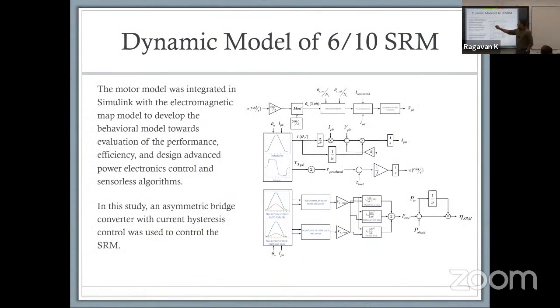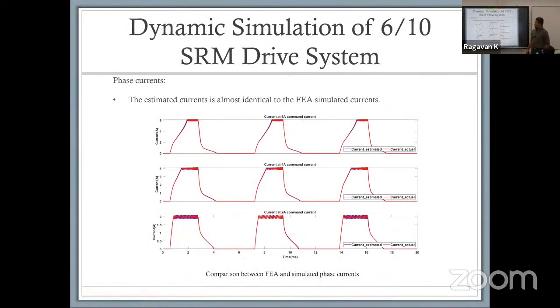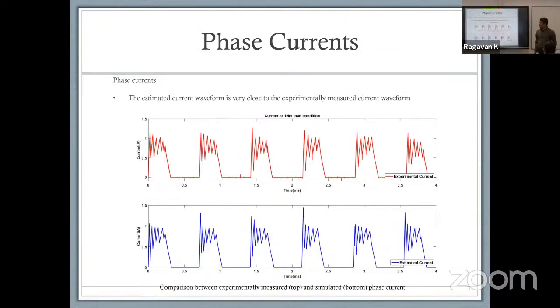So we input that information into our inductance torque flux density model. We added the losses here, and that gave us the overall efficiency that included the loss behavior from magnetics and from my power electronic domain. So the copper losses and core losses were adequately represented. We did check to make sure our numbers were right. We compared the numbers with FEA, the core simulation model we had from FEA, and we compared that with the results we got from our simulation model to make sure the numbers matched, and they matched perfectly.